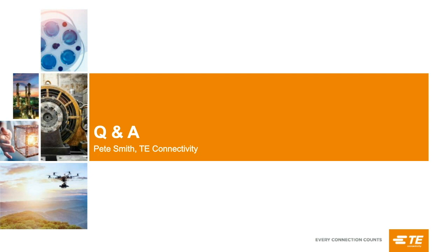So the power you get from those harvesters is proportional to the temperature difference. And so obviously the more temperature difference you can generate, or you can harvest, the more energy you can get. But look for Peltier junctions and Peltier transducers. They're what's used for temperature difference power harvesting.